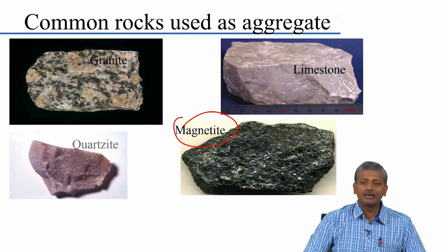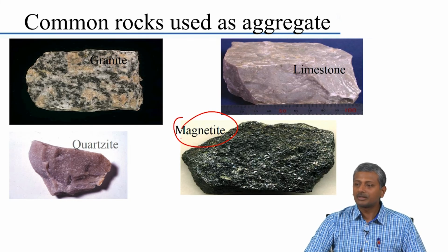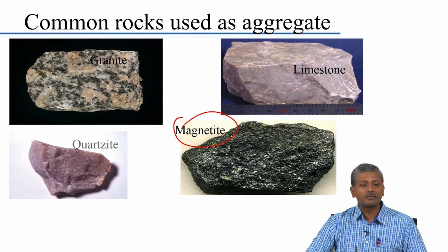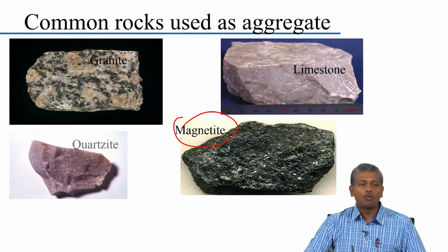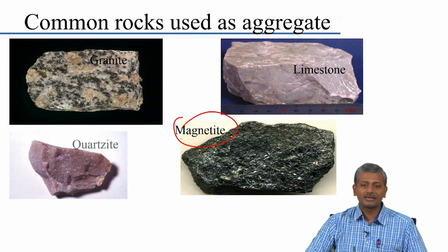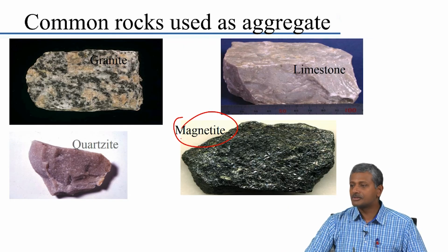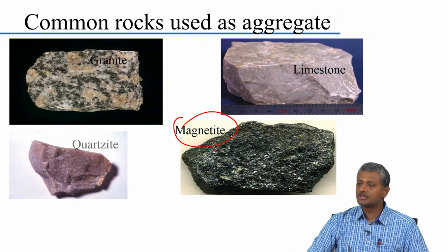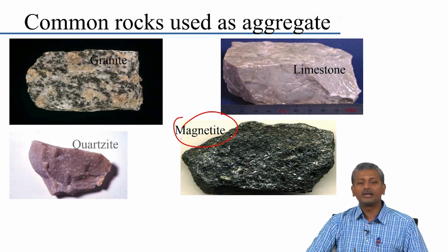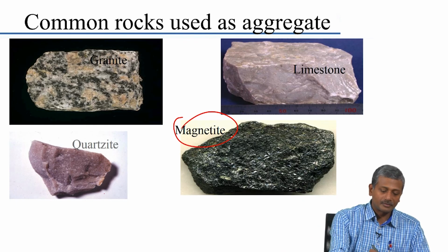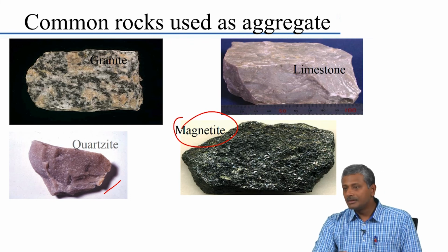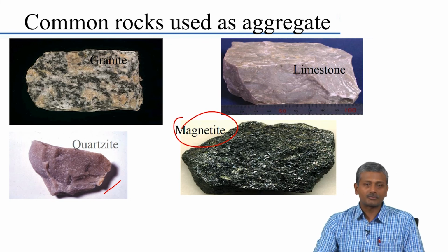It is used in nuclear reactors for radiation shielding purposes, but of course, you can also develop other usages of high density concrete, primarily for designing underground vaults, for instance. Okay, you can design underground vaults, bunkers and so on, but people do not use that as much as high strength concrete. So, high density concrete can also be utilized in other locations, but mostly it is used for nuclear radiation shielding. Quartzite. Okay. Now, from a basic look at the surface characteristics itself, we can tell that there is a major difference between the different types of rocks which can be used as aggregate.